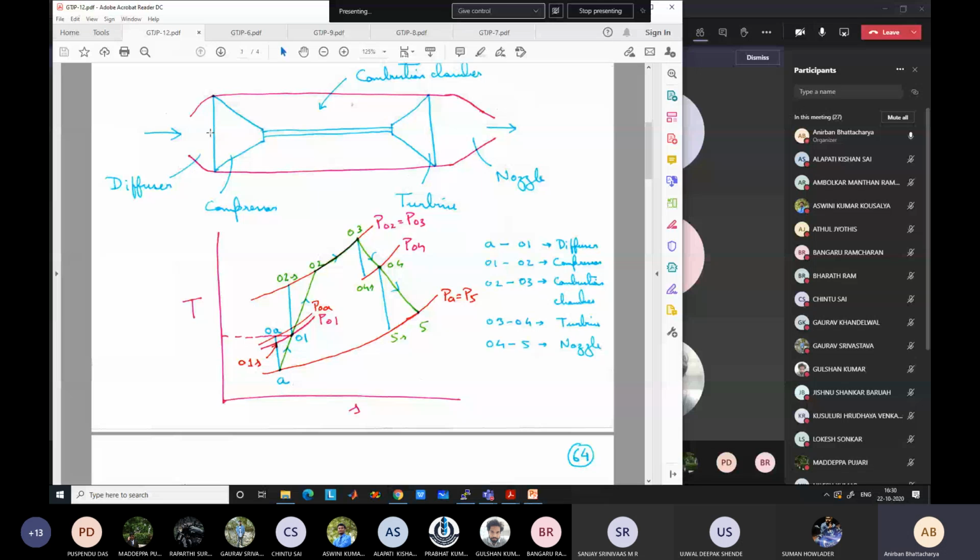So actually energy is still balanced even if there is friction. Even if there is friction, the enthalpy is still balanced. Stagnation enthalpy does not change. Okay. What will change in that case if there is friction, or say you have a flow through a pipe, and there is huge frictional loss in the pipe? What I am saying is that from one side to the other side, stagnation enthalpy does not change. Okay, stagnation enthalpy still remains same.